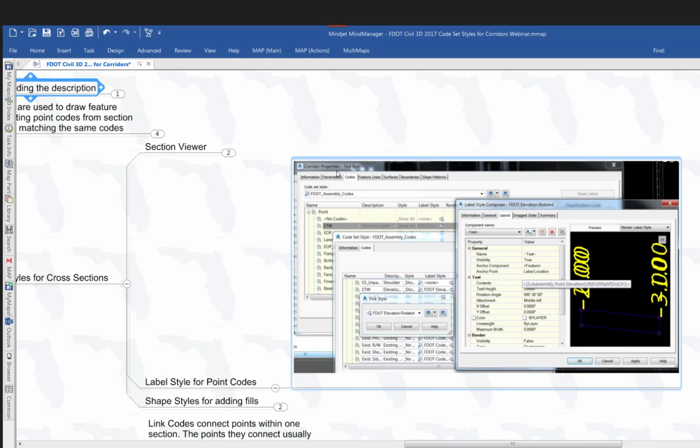So then some other things that are kind of in the same mode as we'd used before: you go into the codes tab in the corridor properties, you find like the edge of traveled way, and then you can edit the code set style. And when you drill down into the actual label style, then in the label style composer is where you actually find this elevation label for the edge of traveled way. So if you're starting from corridor properties, that's one way to drill into what you're going to see as the final output.